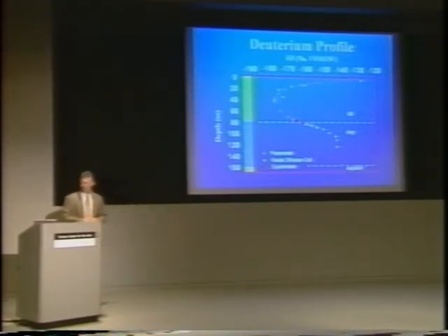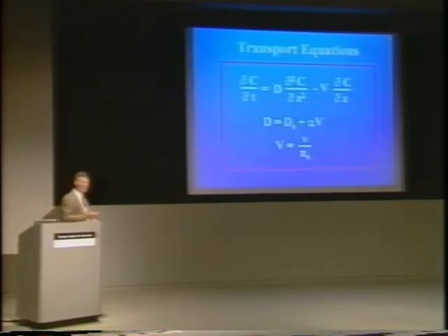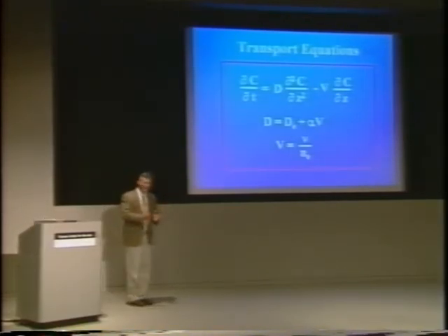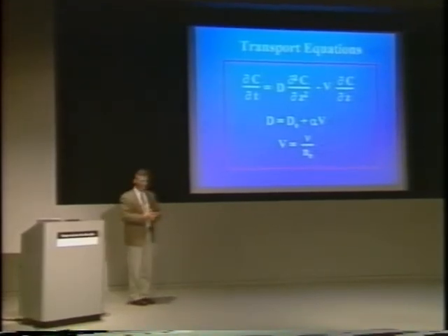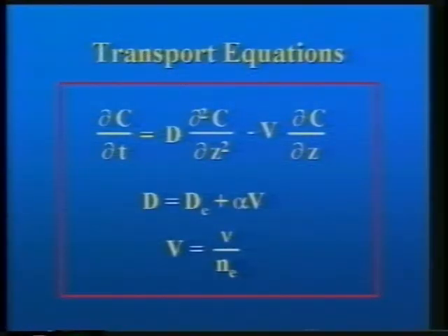So what do we do with these data? Well, the next step is, I've convinced us all that we can deal with a one-dimensional system, so we'll deal with one-dimensional equations. We'll couple advection and diffusion together. To do that, however, we need an effective diffusion coefficient in these aquitards for deuterium. We also need an effective porosity for deuterium in both of these aquitard materials. With those parameters measured, we can go ahead and play what-if games. We can obtain a best fit between simulated data and measured data for different velocities and for different transit times.